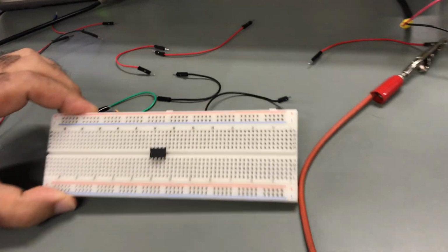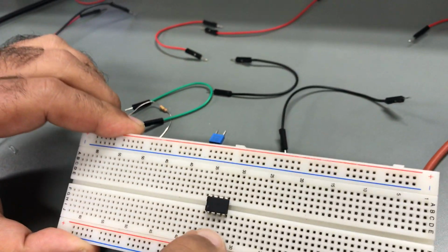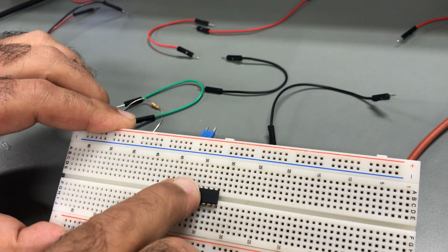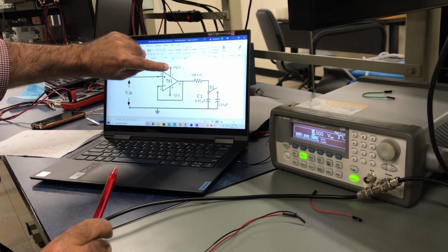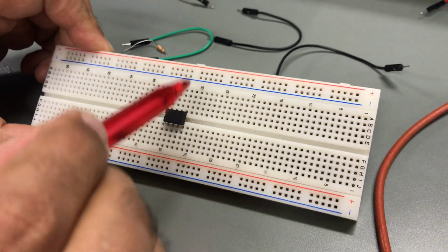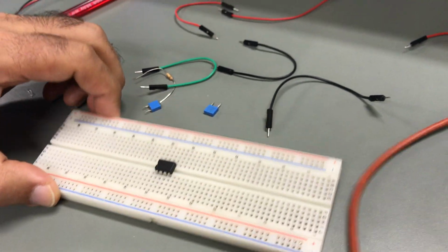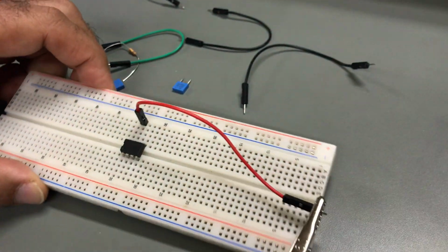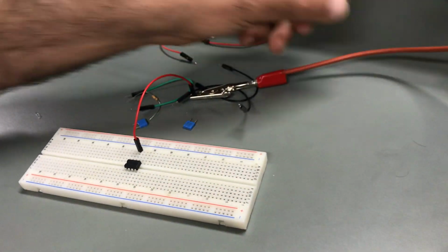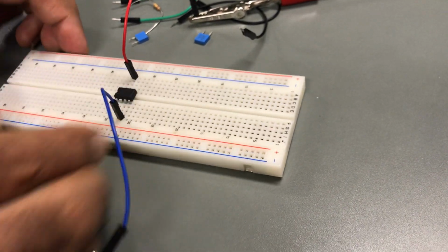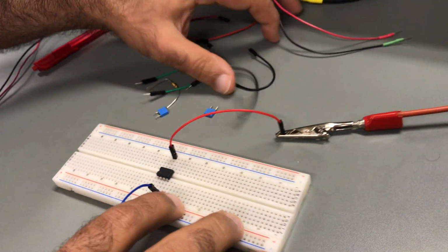So I will connect my power supply here. Like what I told you, this is the operational amplifier that I'm going to use, and I will start counting 1, 2, 3 up to 8 over there. So I would like to connect, like what we are seeing, 7 to 12 and 4 to negative 12. So here 1, 2, 3, 4, 5, 6, 7. This is 7, which is here. So I will connect this guy to 7, which is positive, and I will connect this guy, like what he said, to 4. This is my operational amplifier connected right now.